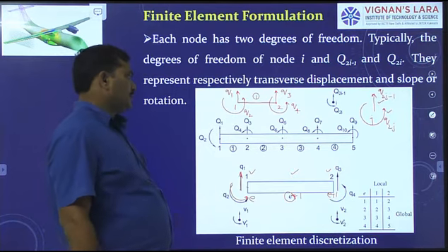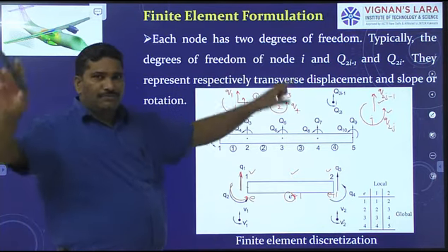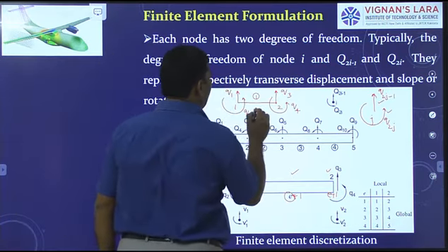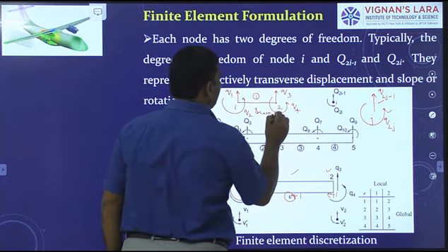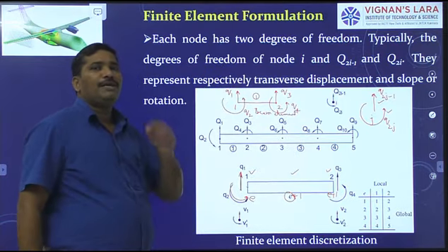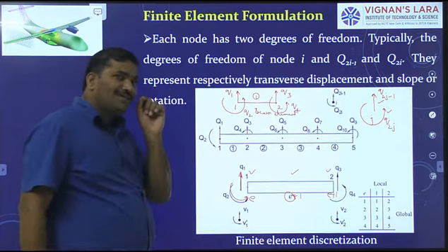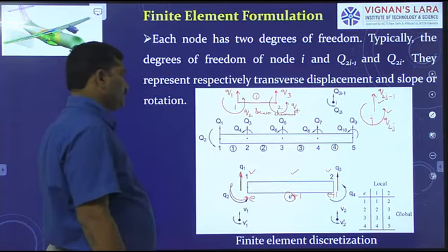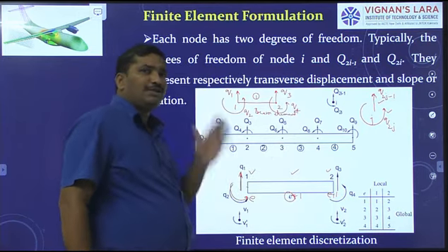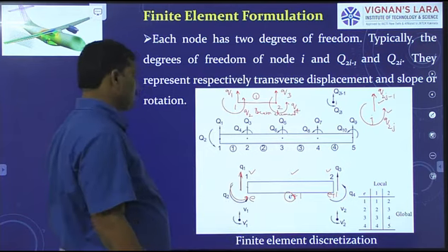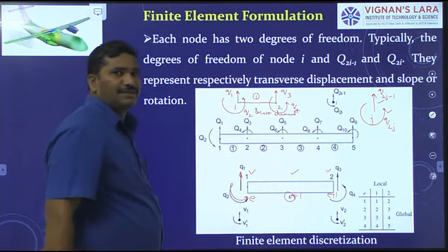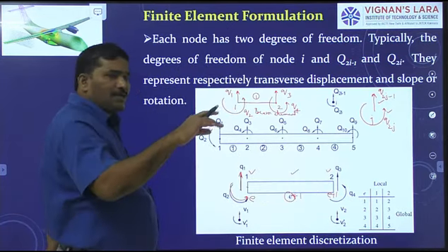Understand? Now, if you have an elastic beam, you have to discretize it into several beam elements. This is the beam element. It is a two-noded beam element with 2 degrees of freedom at each node. When you have a beam, you discretize it into several beam elements. This is a beam of uniform cross section. It is prismatic in shape.